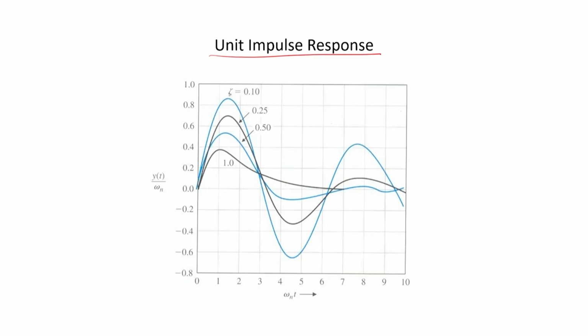So, that means something like this. Let us imagine that I have a mass here, and I have a spring here, and there is a dashpot here like this, K and C. This is a single degree of freedom system, and if I put a force F here, and let us say x is the response at the mass m, then I can write down the free body diagram: the force F is applied, and there is an inertia force.